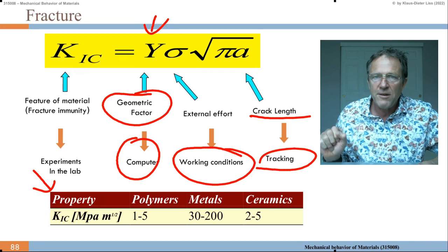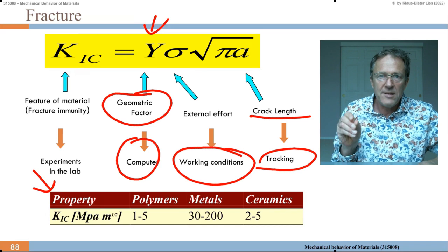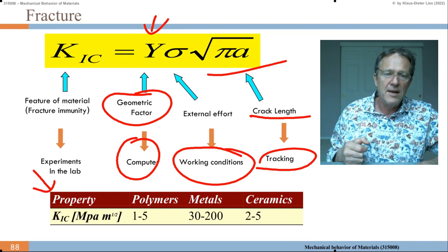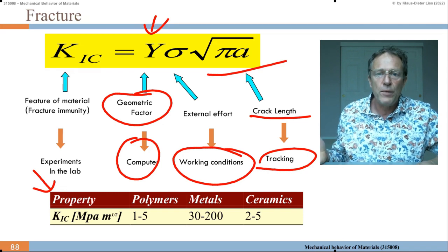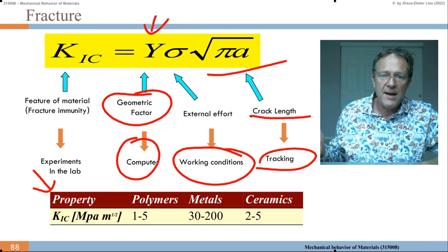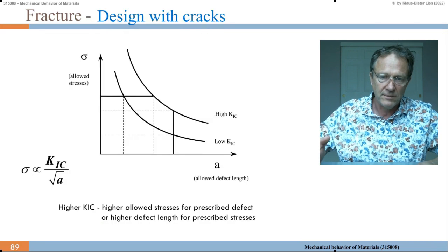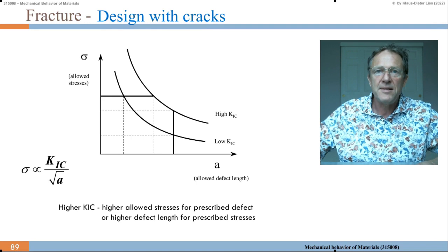And if you find cracks, then you determine, okay, they're underneath a certain length limit, or they surpass the length limit and may lead to a crack. And then, of course, with the safety factor, you replace the part. You have to repair it. The airplane is designed with cracks.